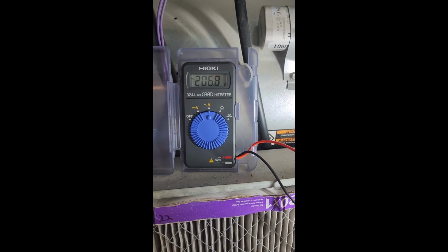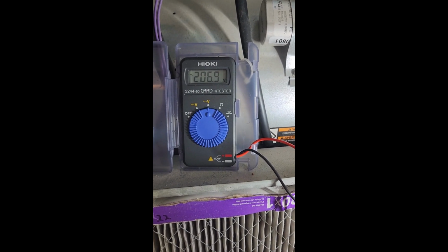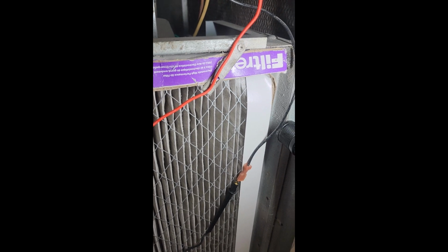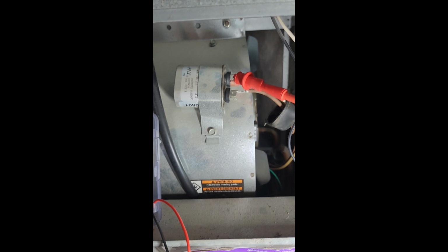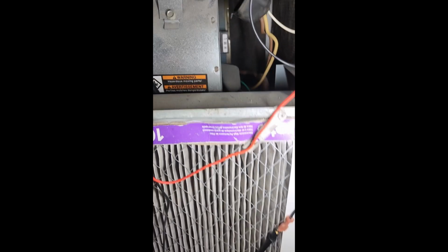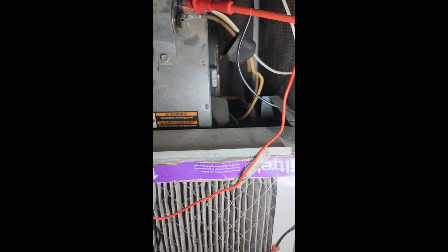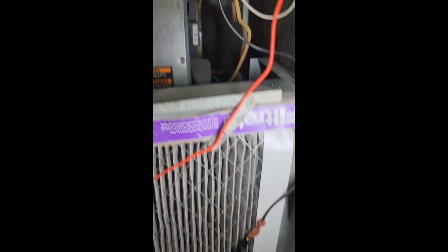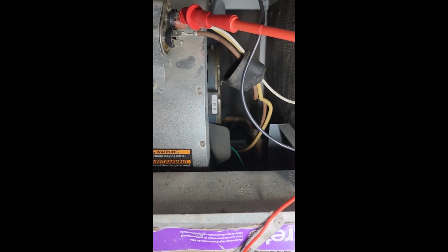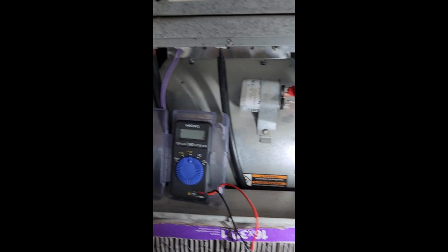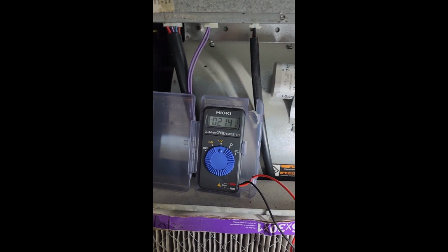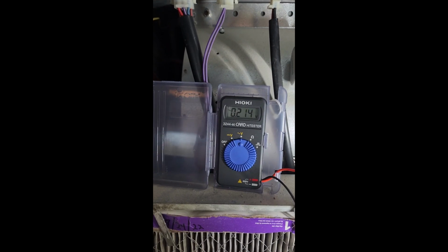So once again, we know that we have voltage going into both the top part of the start capacitor and to that high, medium, low switch. So now, before we do any more digging on the start capacitor, I'm just going to try something really obvious. I am going to move this connector to the high position just to see if anything changes. Of course, we're going to power this off first because I do not want to get hit by 200 volts, for obvious reasons. So let's try that.